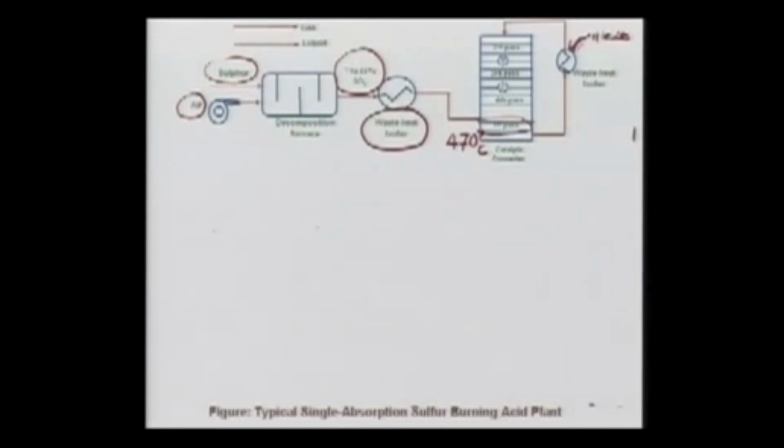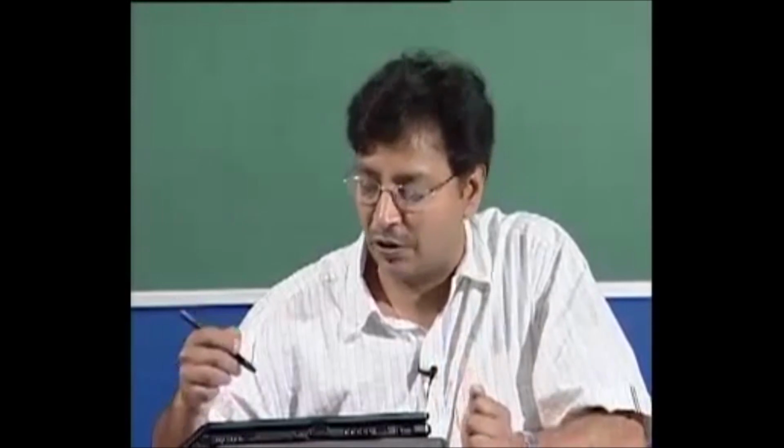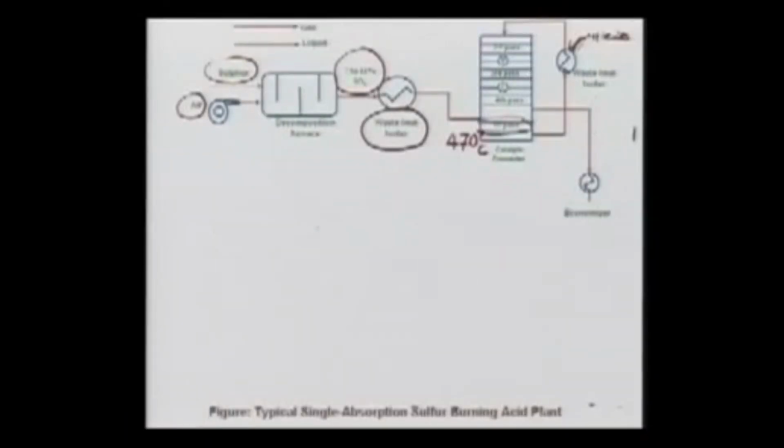Heat recovery. Again it passes to the second stage of the conversion, and again more heat is developed, because SO2 goes into SO3. This heat is recaptured, and then you go to the third step, and again heat is recaptured. So in the process we are trying to convert SO2 into SO3 at various stages, and in every stage when the heat is generated we capture the heat. So finally, largely you see here most of the SO2 is converted to SO3.